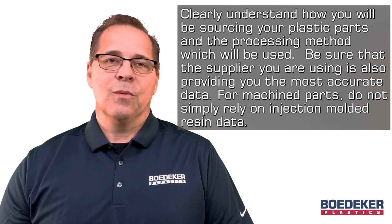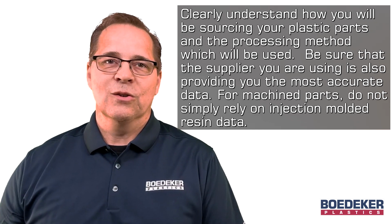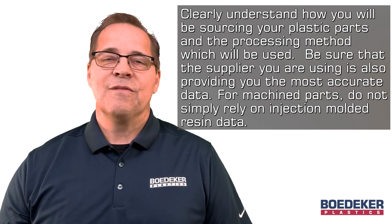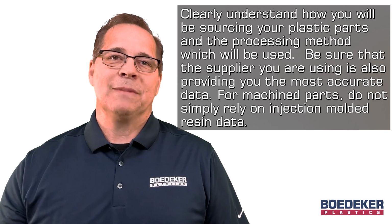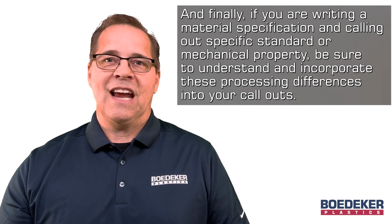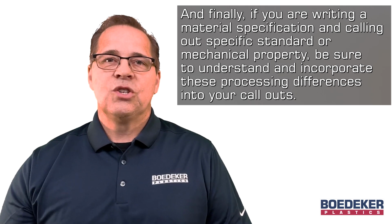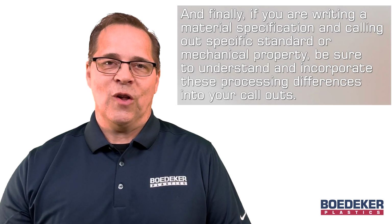Clearly understand how you will be sourcing your plastic parts and the processing method which will be used. Be sure that the supplier you are using is also providing you the most accurate data. For machined parts, do not simply rely on injection molded resin data. And finally, if you are writing a material specification and calling out a specific standard or mechanical property, be sure to understand and incorporate these processing differences into your callouts.